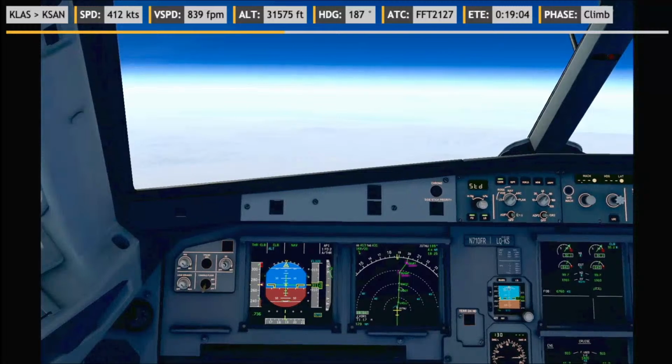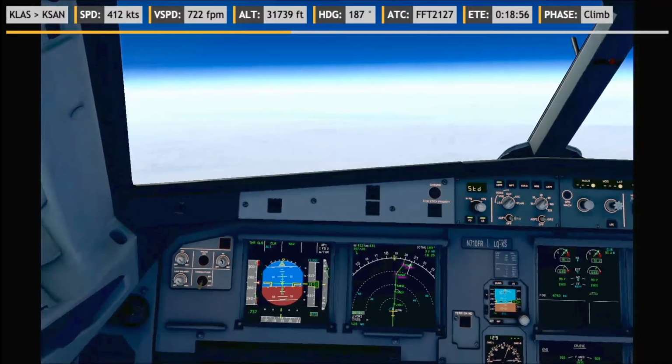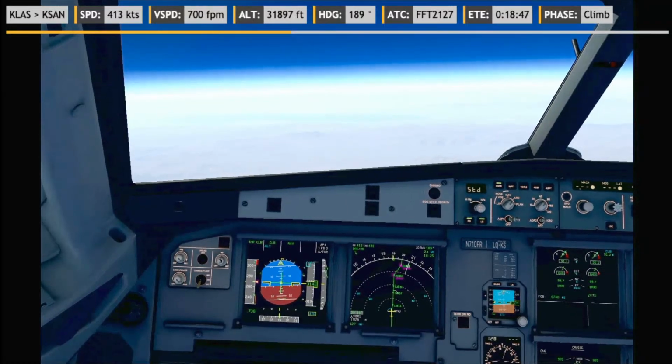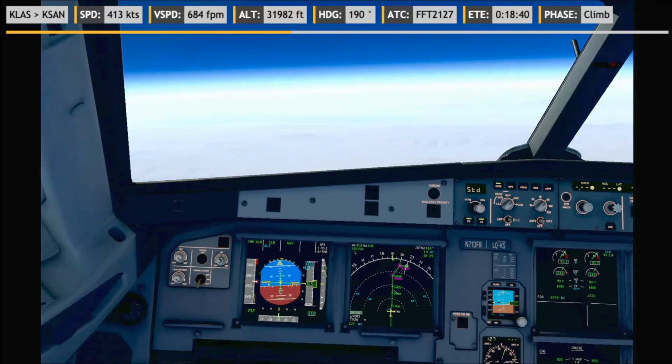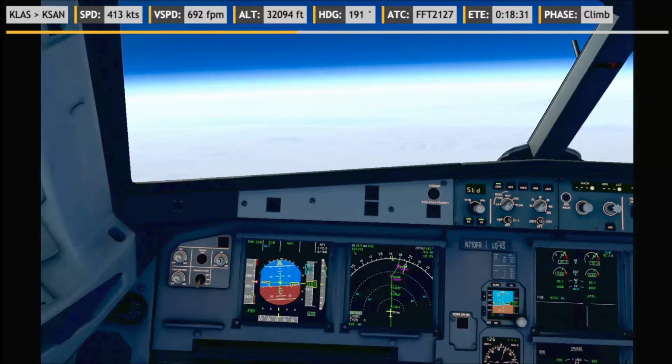And we don't have any vertical guidance, and I don't see a table of altitude versus distance, which is a little bit annoying. Normally you get a nice table, altitude versus distance, then you can see at what point you should be at what altitude, but this doesn't give me any. So I need to get about 1,000 feet a minute apparently. We're going to be around 860 feet a minute is what it's saying that our descent rate should be. So we're approaching our altitude there. It's 400 to go. Standard is set.